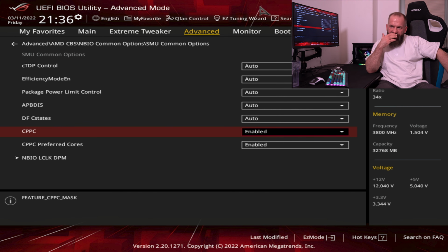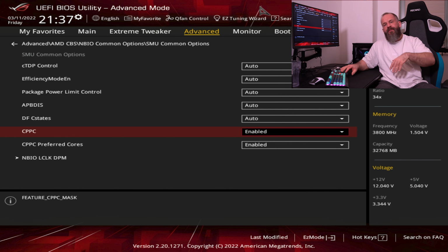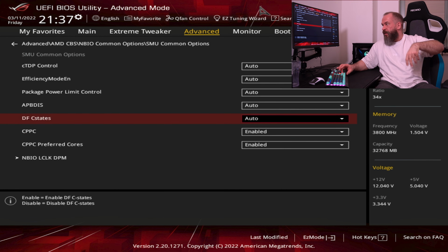Now some people say, yeah, but it's only if you use the curve optimizer. That's not true. Basically, it's just the general way the communication works and how the setting is made by AMD for your CPU, for the control of the workload for the cores. It knows which cores are preferred, the ones working well with low voltage, high throughput, low latency. When the workload is rising, the preferred ones get used first and the worst ones get used last. That's what you want, of course: low latency, good throughput, nice performance.